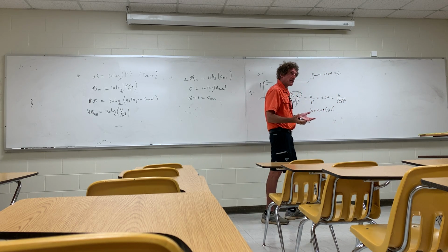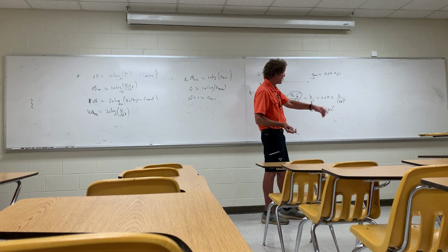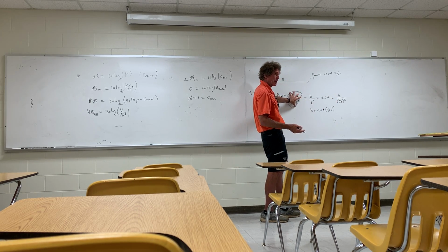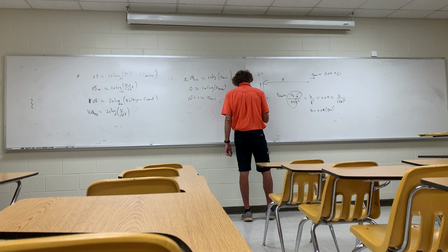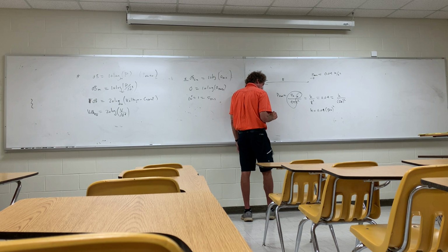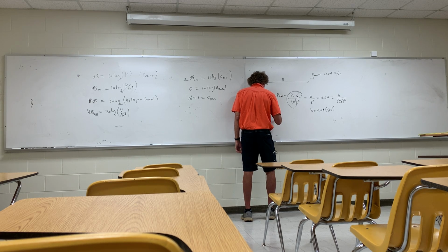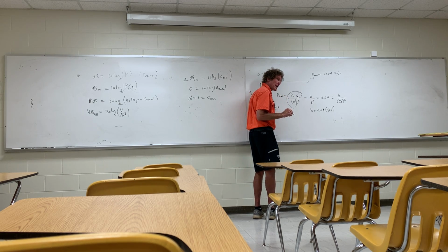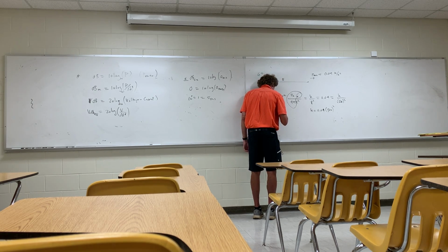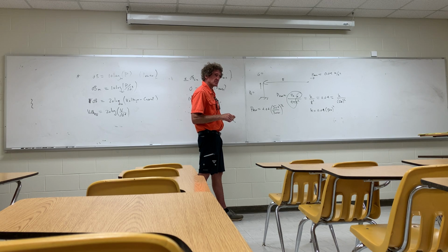Y'all agree with that? From that point on, at any distance, I can tell you what the average power density is, because I have K. I have this constant, which is all this stuff. Everybody follow me on this one? All right. So then they ask for the average power density, how far away? That's general EMAG, by the way. What range? 2 kilometers. All right, so now I put in K, which is 0.04 times 500 squared, divided by 2,000 squared. Do y'all agree with this?